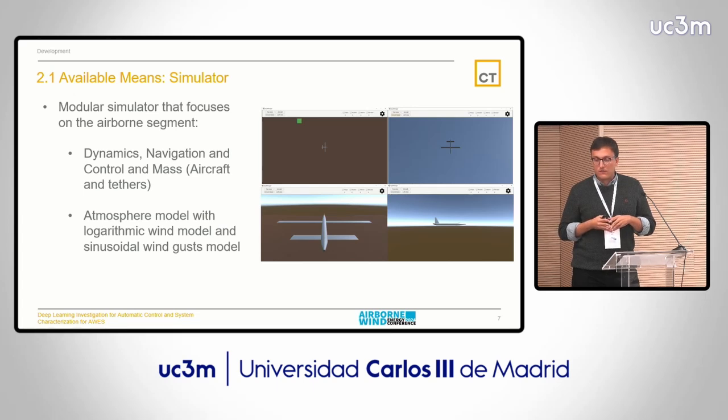In the simulator, we have also an atmosphere model of the international standard atmosphere with a wind model, a logarithmic wind law, and it can also include gusts that are modeled with a sinusoidal wave with a set probability of activation.